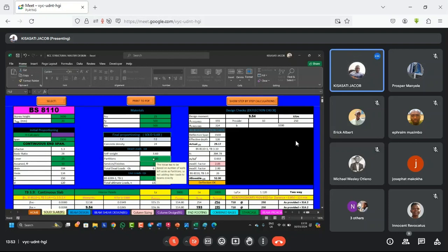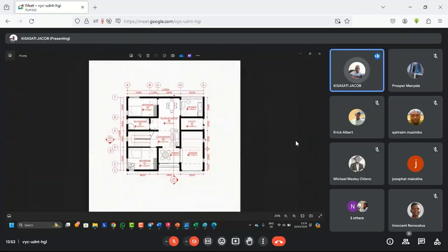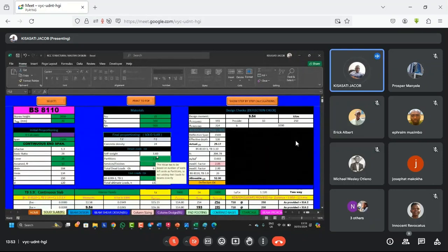So in that range, what do you think is the load for this building? As you can see, there is actually no load, unless the client comes up with a small partition to include his bathroom inside this bedroom, then we can treat that one as a partition load. Otherwise, for that building, there's not much partition load, so we can just use 1 kilonewton per meter squared.